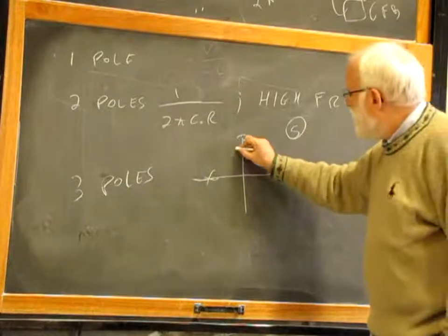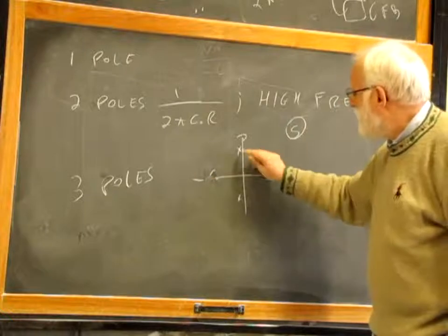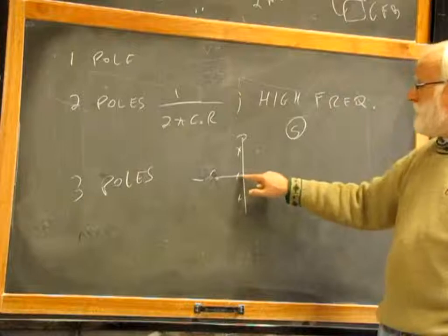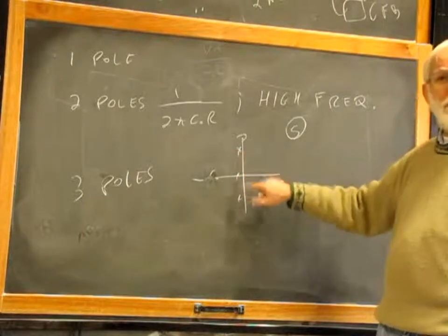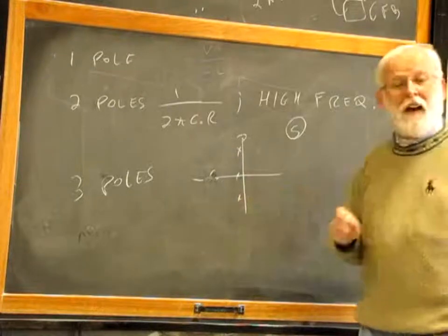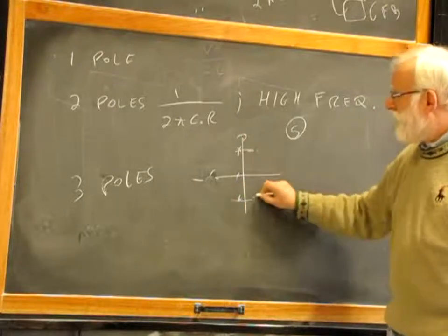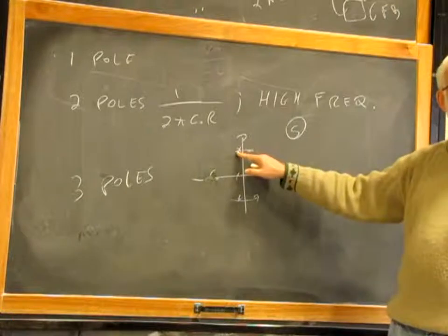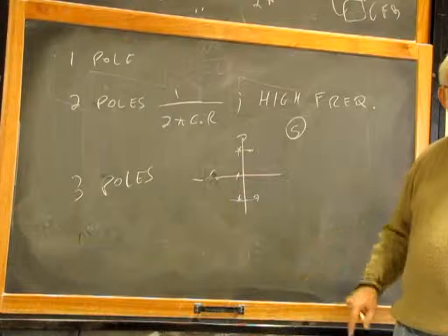And these 2, this is a slow pole, a low frequency pole, so it's close to the origin, and the 2 complex conjugate poles are high frequency poles because they are 1/2 of the switching frequency. And according to the duty cycle, these poles can move to the right-hand plane. When the duty cycle equals 0.5, these 2 poles move to the right-hand plane and the system becomes unstable.